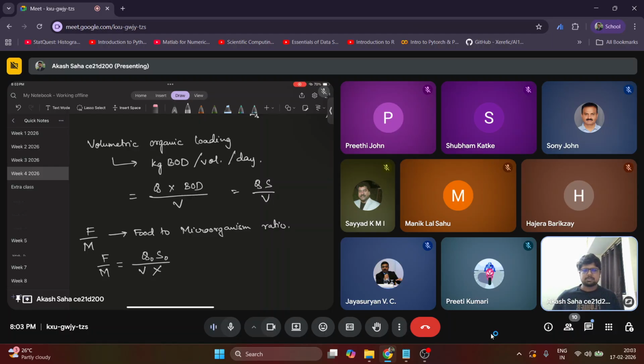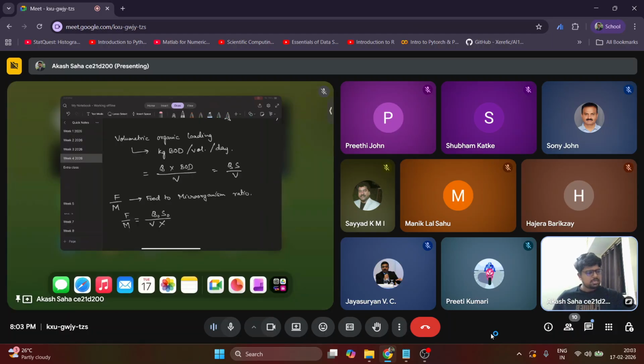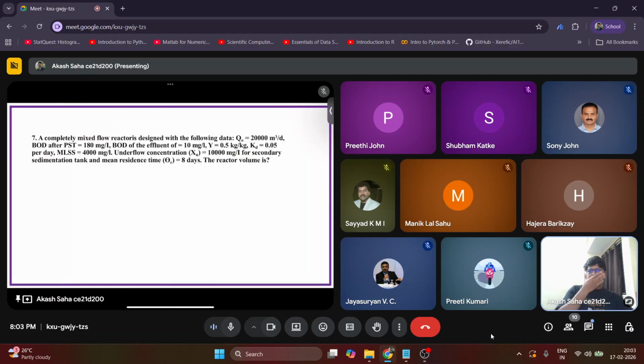So these are some of the things that you should know. Now let's come back to the problem. So many parameters are given: Q naught, BOD of effluent, Y, KD, everything is given. Now you have to find out the reactor volume. Can you solve it now? I'll wait for some time. 2428.57. Yes, exactly. That is right.